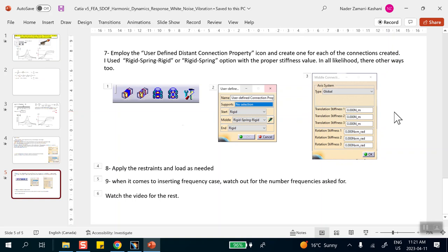In other words, I take, for example, aluminum, put it on that beam, and then the Young's modulus of aluminum, which is 70 gigapascal, I change it to 0.1 so that it has no stiffness effect on the spring element. And the same thing with the mass. So I reduce the mass from 2,700 kilogram per meter cube to 0.1. So basically, it's a massless beam. Okay, so let's go ahead and do that.